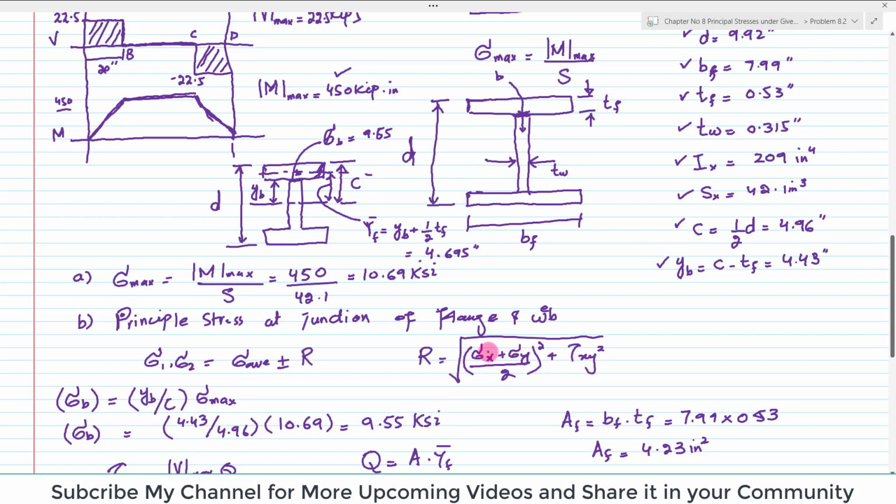Here you will need the normal stresses and shear stresses. So first we will find the normal stress at point B, the junction, and the shear stress. Once we have normal stress and shear stress, you can use them in the formula of principal stresses and calculate. So let's move toward finding the normal stress at this junction point.